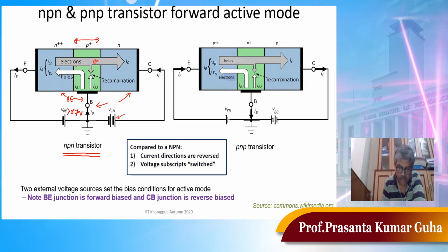As electrons are moving from left to right, let's look at the base emitter junction again. Electrons moving from left to right generate a current in the direction opposite to the motion of the electrons, and I have designated that as IEN, right? What about the movement of holes?